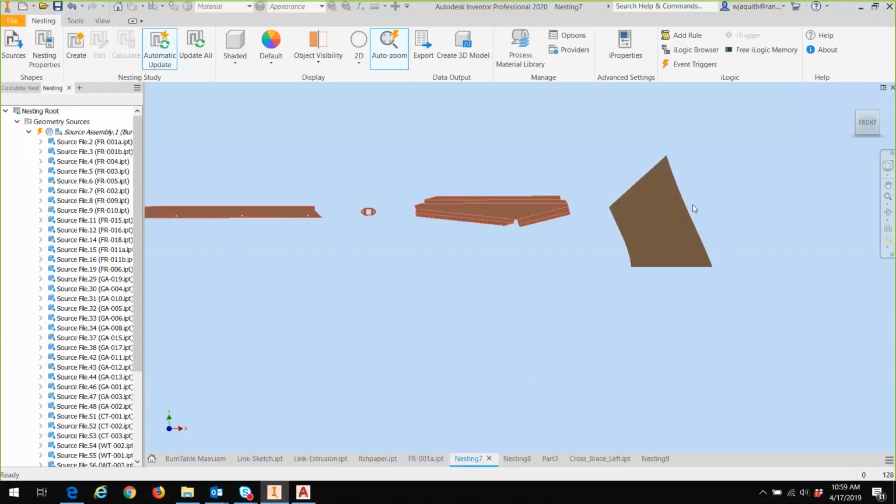Awesome. Okay, so what about common line cutting? Joshua Martinez had a question about, can you nest for common line cutting? Yeah, so it's a single pass. The parts share a single edge that the laser would go by and cut. I assume it would be basically a nesting at depth 0. Those parts would be right against each other. Can we set that to 0, or again, would that have to be done in the DXF file?